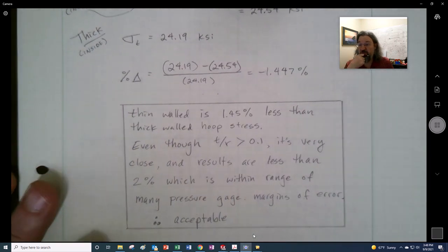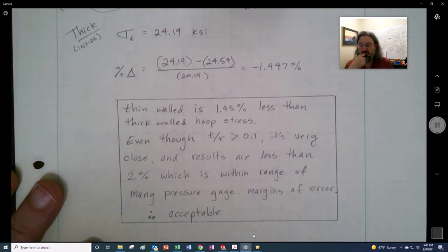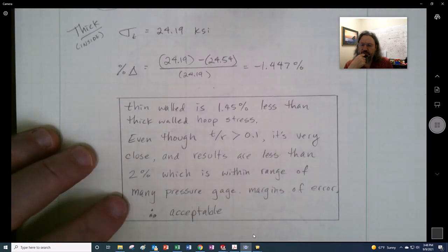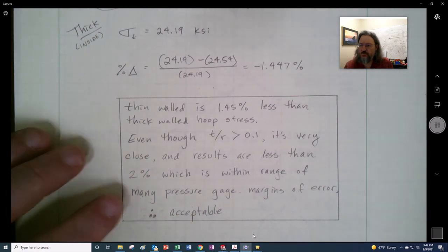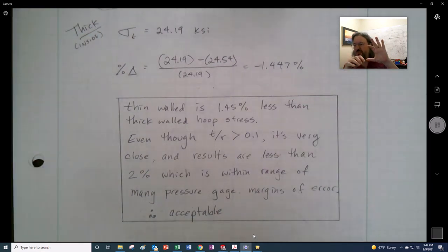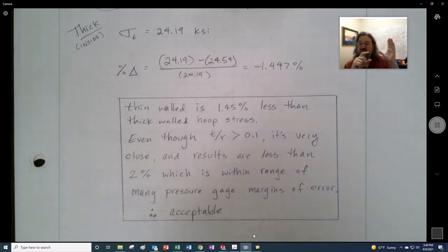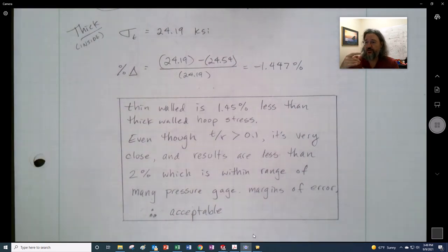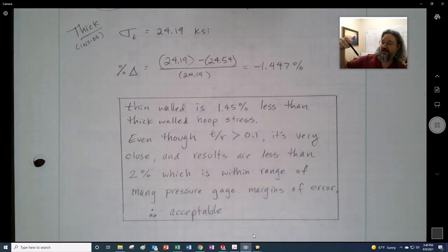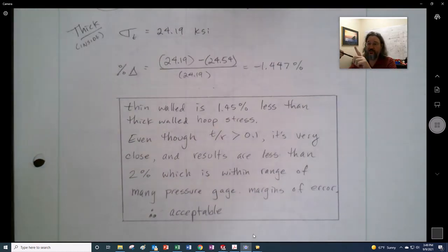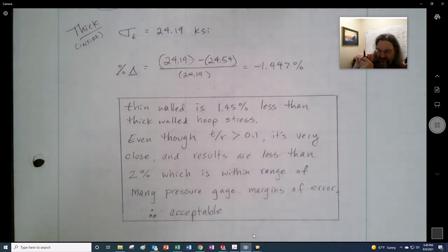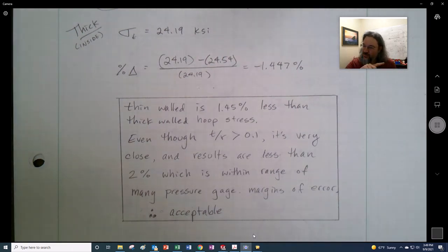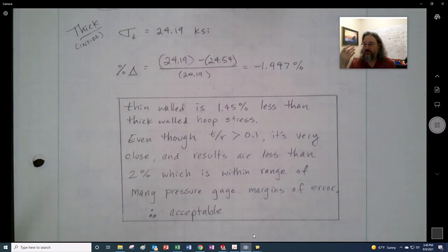I mean, in judgment or experience. For my judgment, and there's no reason that you would necessarily know this, but if you ever go to a pressure vessel that has, especially, an analog gauge, just look at the gauge and read the pressure. Tell me how accurate that pressure is. Well, there's something called parallax error, right? Where if you're looking straight at it, it looks like one thing, but if you go to the side, you can change the answer just by looking from the side of the needle, right? Because the needle's not touching the back plate of the thing. They call that parallax error.